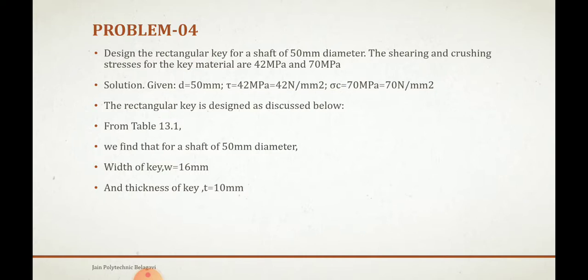Design the rectangular key. The problem says we have to design a rectangular key. Designing means we have to check the stresses and find out the dimensions; that itself is the design. For a shaft of 50 diameter, we have to design a key. The shearing and crushing stresses acting on the key are given as 42 megapascal and 70 megapascal.